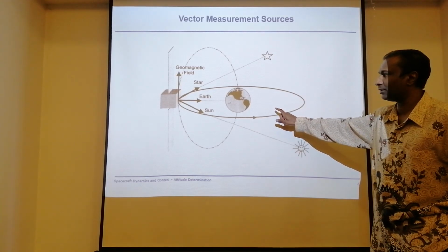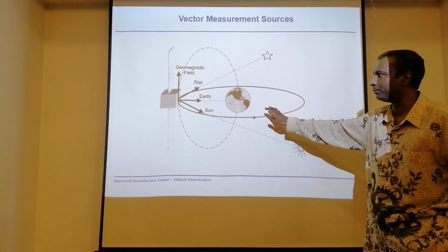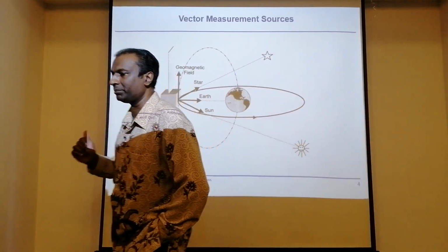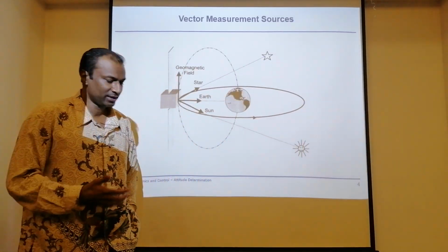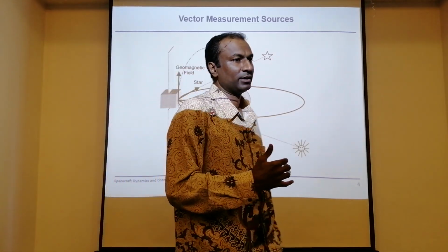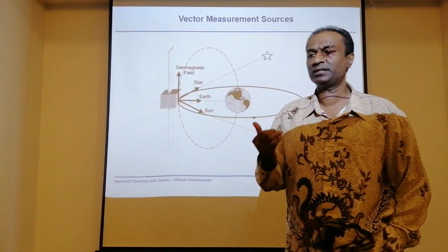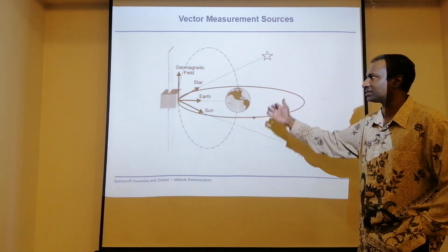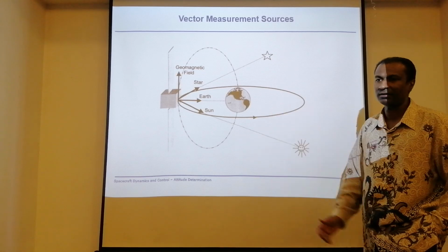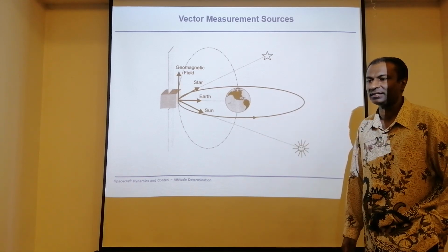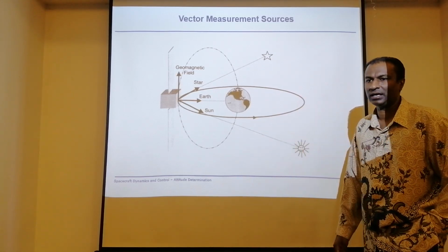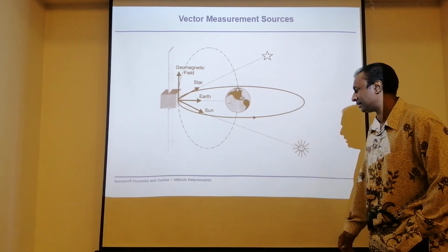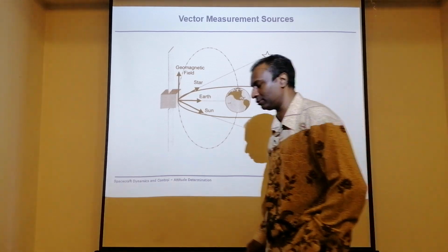We don't put anything related to the gyro here, because the gyro works on attitude rate, so it doesn't depend on an external source for information. That means it doesn't use the sun, a star, the geomagnetic field or planet Earth. With a gyro, you don't need any external indicators. It detects angular rate, and then from there you do an integration to find the attitude you want.